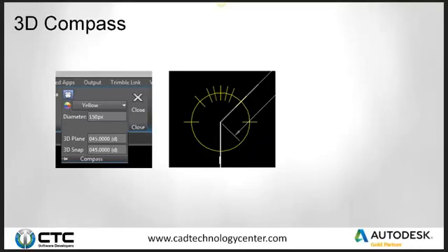It's hard to do that with the compass, so we'll have to use the polyline feature for that, and we're going to get into the examples of that at the end. The cool feature with the compass is if you go to an ISO view or model view of your drawing space, your model space, when you have your compass available, you can hit the P and it'll actually rotate your compass.